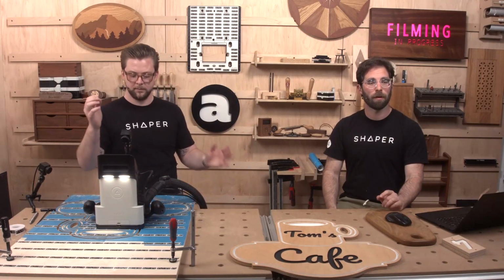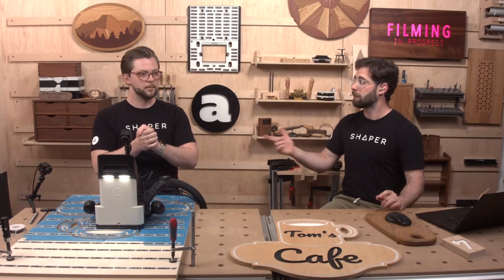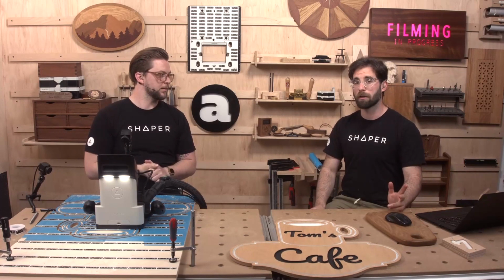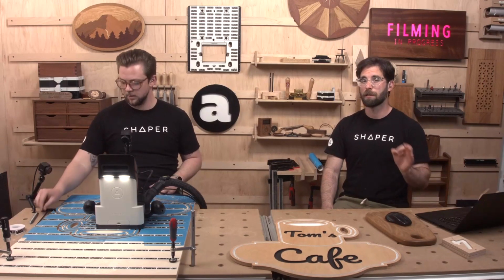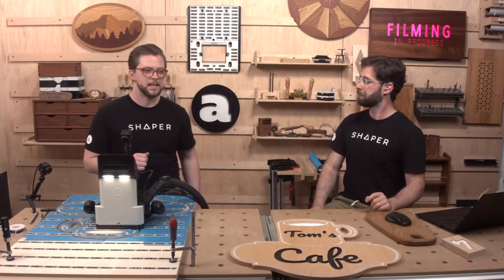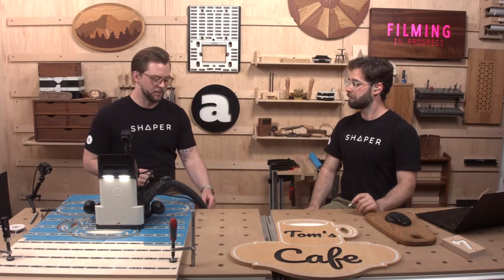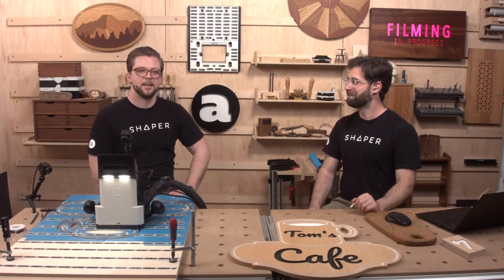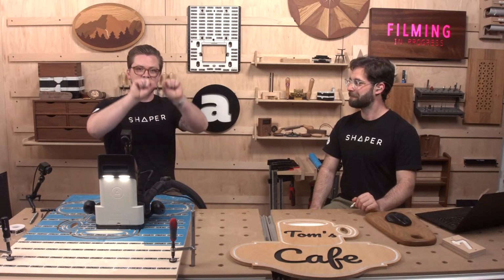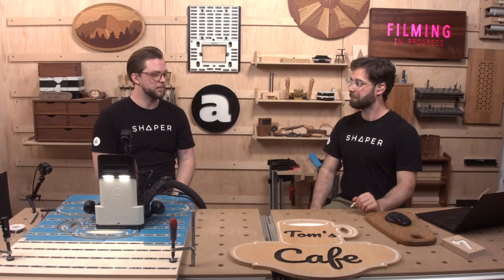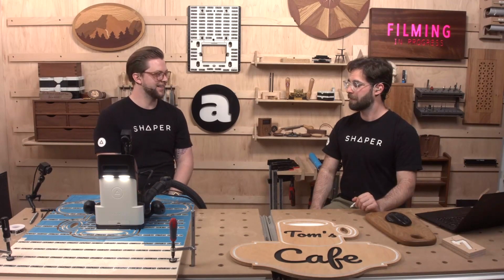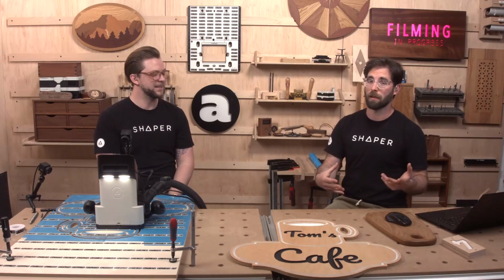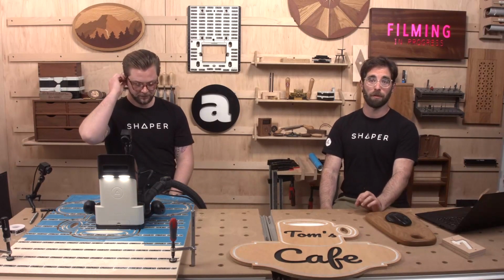I'm looking over at the sign over here. We really like 16th inch router bits for detail work. Oh my gosh, yeah. If you're working on a small sign, 1/8 inch is good. 1/16 of an inch really gives you crisp corners. Yeah, and so much of the text and stuff we want to do, if it has any kind of serif, you're going to need a tiny bit to get into that little transition point, and it looks really crisp. A 1/16 of an inch, it looks like a sharp point if you take a step back. Yeah, and there's something about bigger signs compared to smaller signs, too. The smaller the sign, the more important those small router bits are going to be.